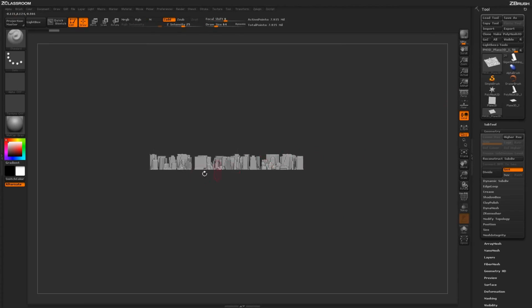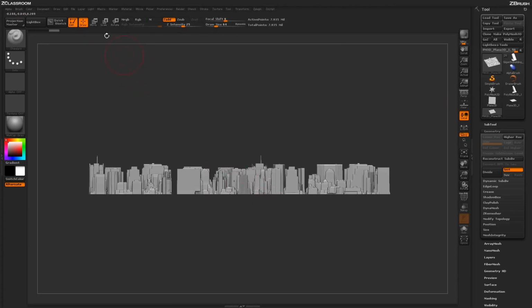So I'm going to turn off perspective and come to the side like this. Then I'm going to navigate up to the top to this Move button, or press W on my keyboard, and activate the Move Transpose line. With the Move Transpose line selected, I'm going to hover over a lower part of the city, around ground level, click and drag up in a vertical fashion, and while I'm dragging up, I'm going to hold Shift, and that's going to lock this transposed line into this vertical aspect, like so.